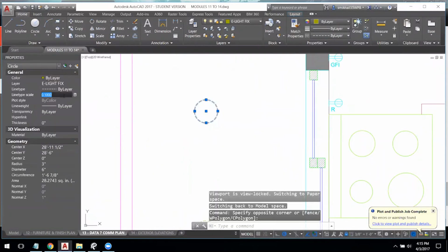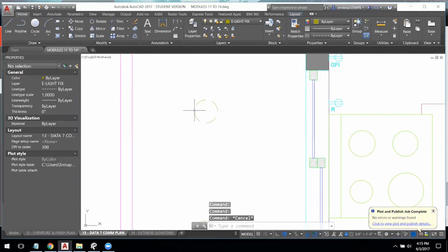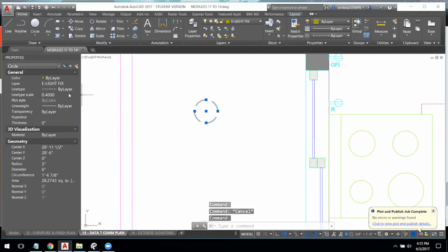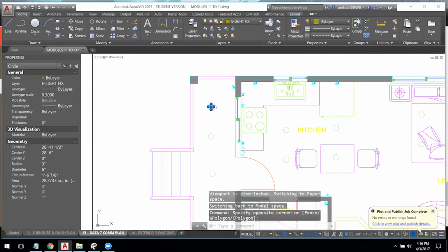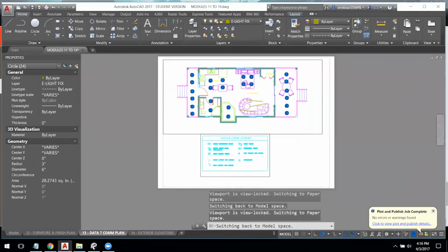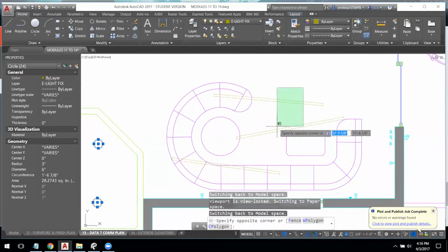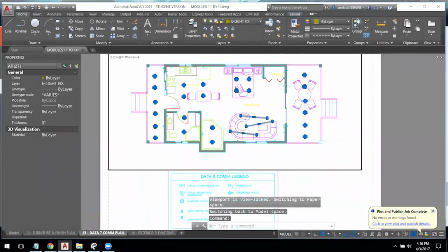So we'll take this and let's try line weight 0.05. That's too close. Let's go up. Let's do 0.5 or 0.4. Okay. Just want to get about 6 or 8 dashes in here. So let's try 0.3 this time. Okay, that looks about right. So one more time, select the object, right click and select similar. Let's go back in here and selecting the remaining of the light fixtures and set the LT scale to be 3.